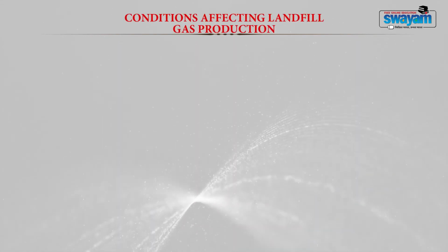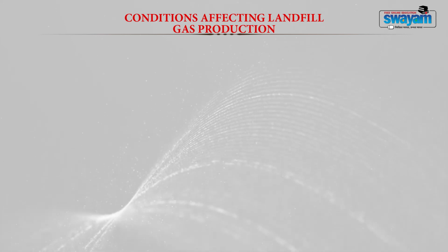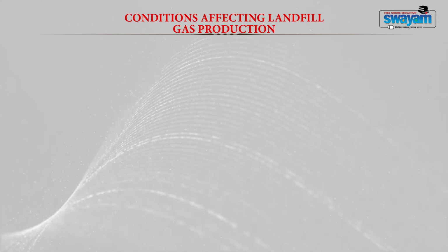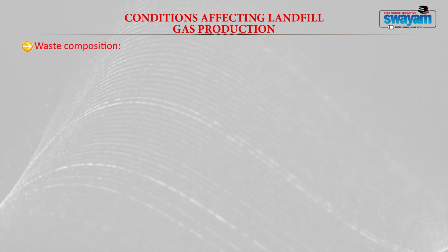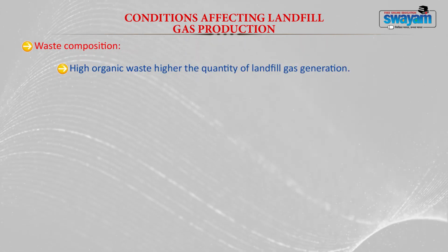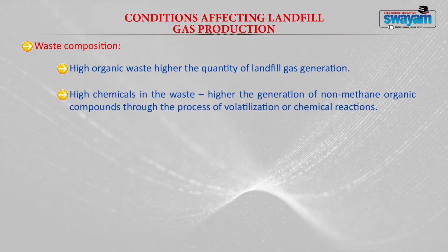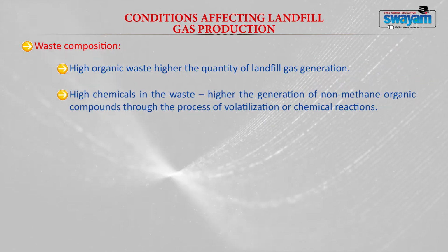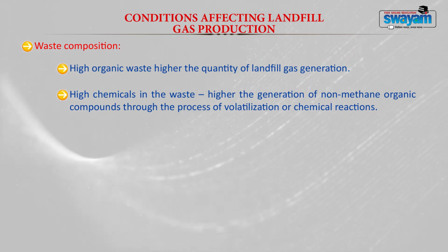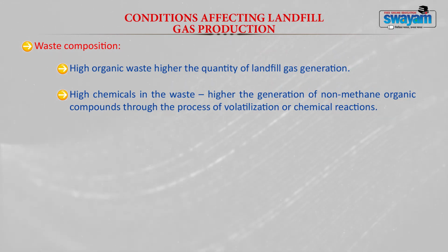Now, let us discuss what the different conditions are that affect or influence your landfill gas generation. First is your waste composition. The higher the organic waste, the higher your landfill gas generation. If you have a high amount of chemicals, then you will have higher generation of non-methane organic compounds by the process of volatilization or chemical reaction.